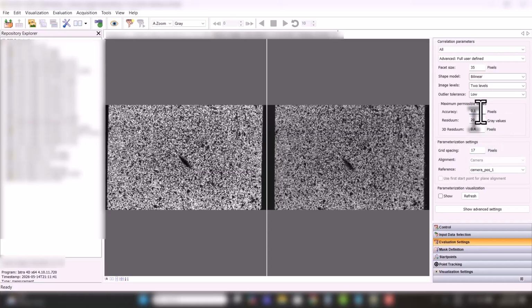Something else you can do is, what we're doing here is we're trying to run quick correlations so we can test out, I'm doing that for the sake of this video, but you would want speed to do this quickly because you're testing out facet sizes and mask definitions, etc., right? Especially when it comes to the notch refinement and crack tip refinement. You're wanting to do these quick correlations. That's why we condensed down the total images. Well, if you make the facet spacing too small, then that really slows down the correlation time.